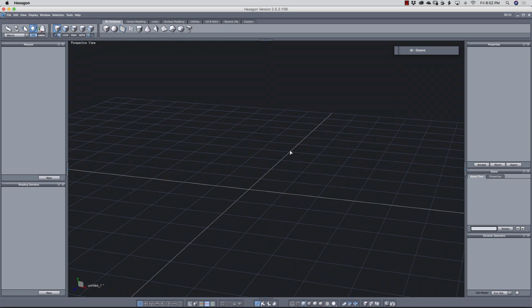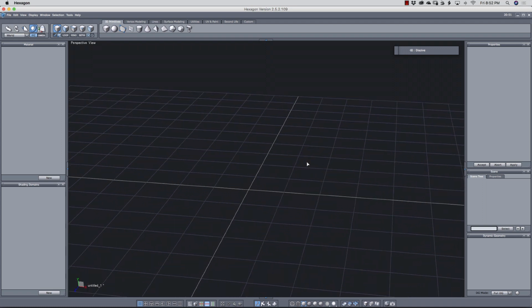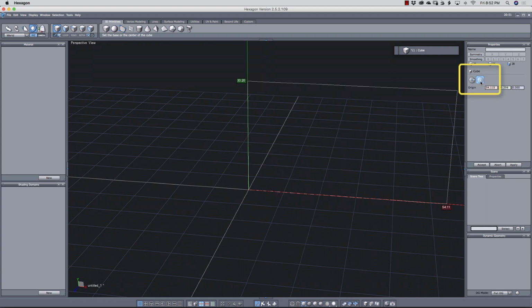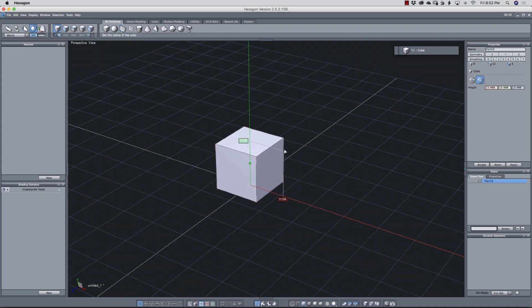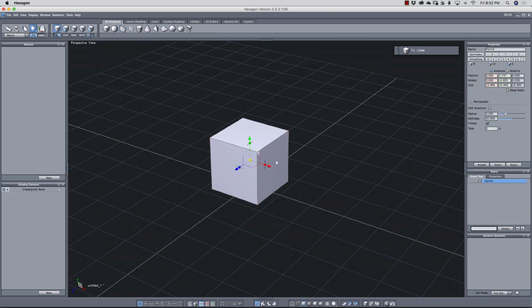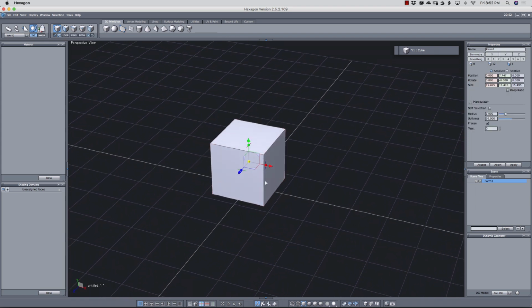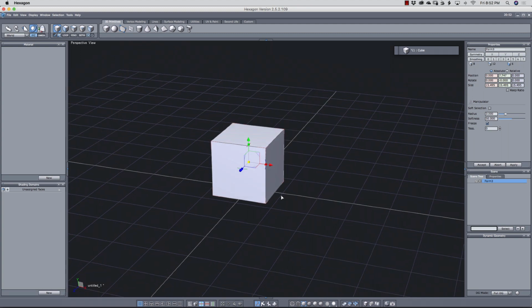Okay, let's get started. Let's place a cube in the scene. Press Alt-1. Then look over here, make sure your origin is set to this, the base. Hold Shift, click here, and that will snap to the center of the world. Left click, scale, and left click to place it down. This will become the body of our jet.